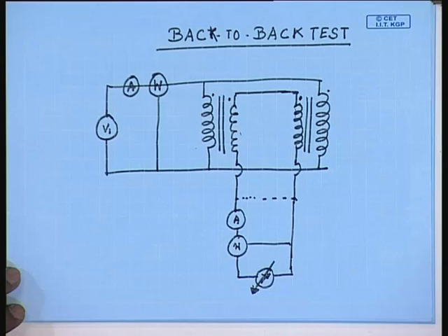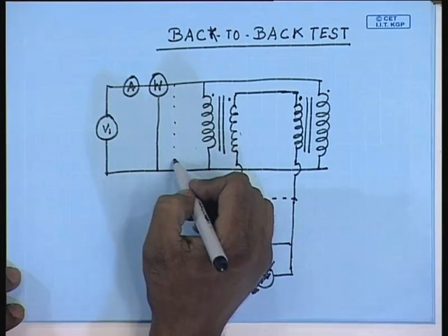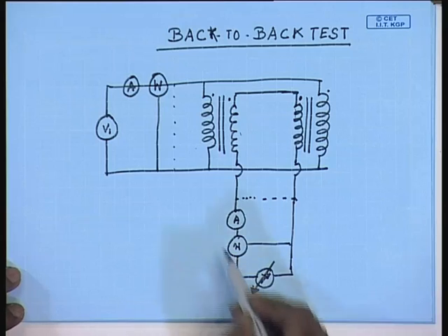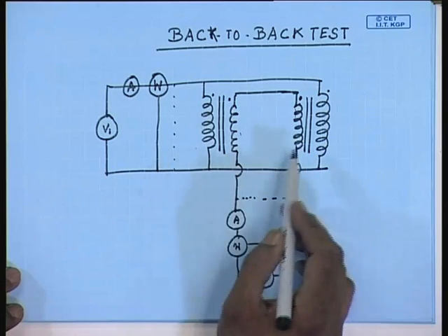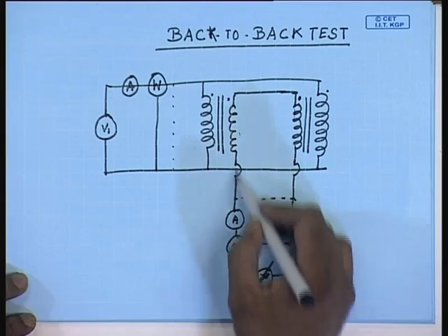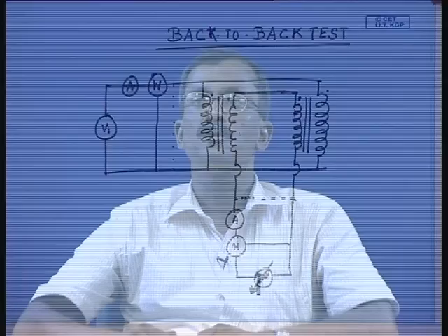Similarly, if we short the source V1 and consider the contribution of the source V2, we see that the current flowing in the secondary windings will see two shorted primaries coupled to them. Therefore, the current flowing through the transformer can be controlled by controlling these voltages to be the rated current of these two transformers, and the power drawn will be the copper loss of the two transformers.